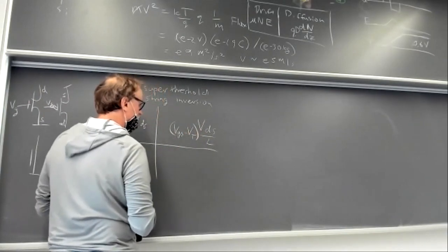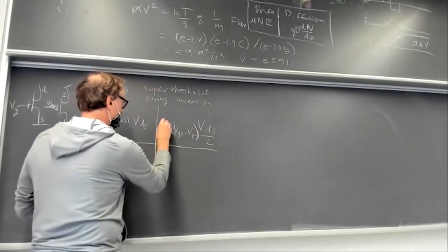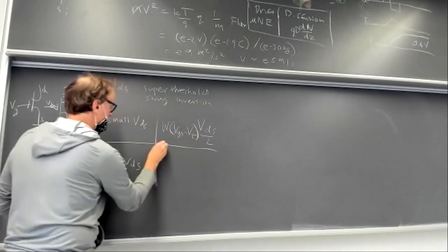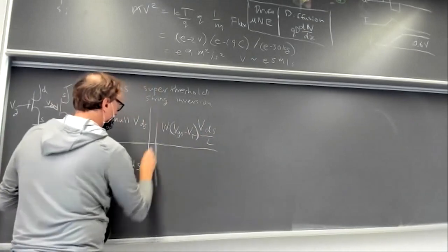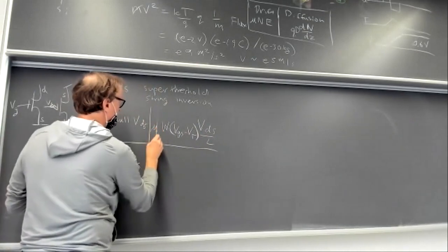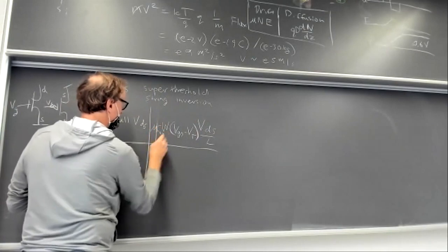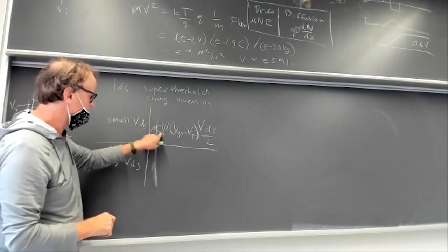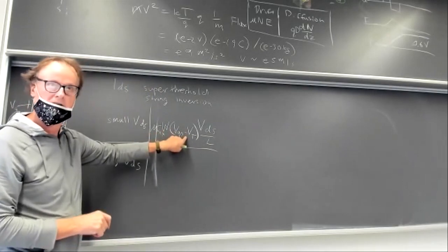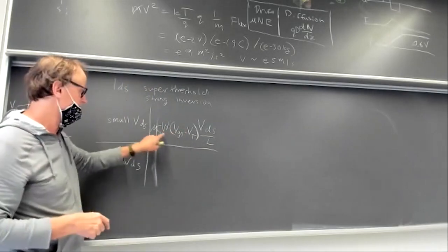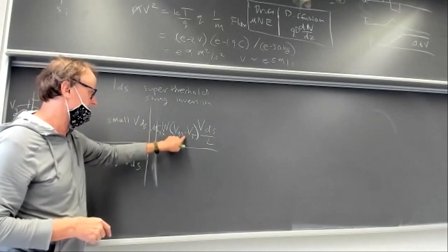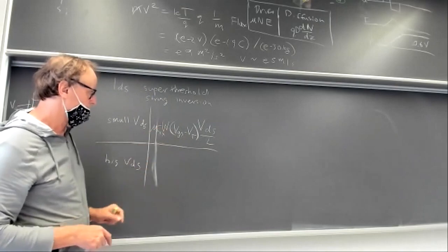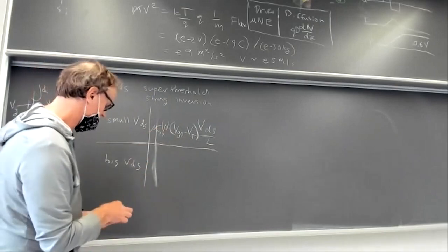Yeah. And then the current is also proportional to the width of the transistor, the mobility, and the oxide capacitance. Because the bigger the oxide capacitance, the more charge you get per unit voltage, right? The definition of capacitance is that the charge is equal to CV, right? So let me try to explain where this equation comes from.